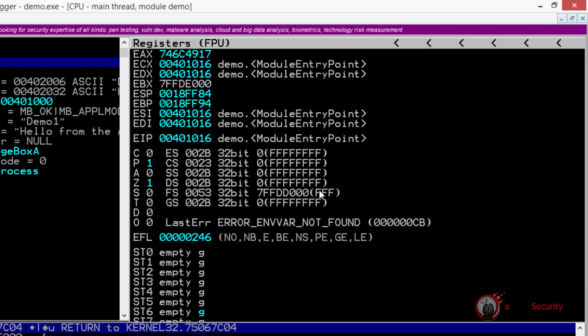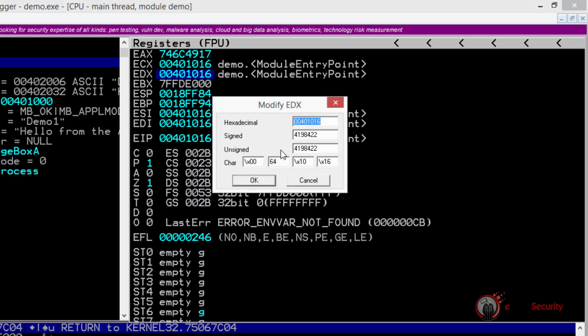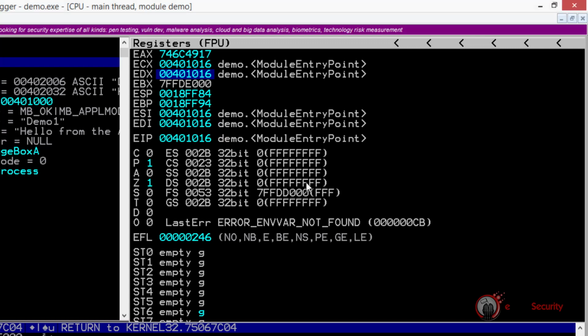Here we can see all the registers and their values. Similarly to the disassembly area, we can double-click on the register value in order to change it. This can be very useful while debugging the application. For example, if we are debugging an instruction that tests if the register is set or not, we may change the value of a register and force a different flow of the program.